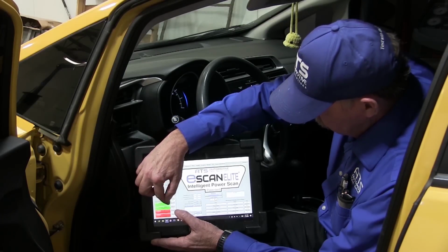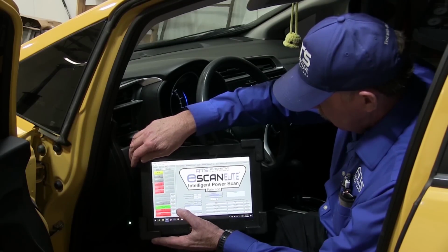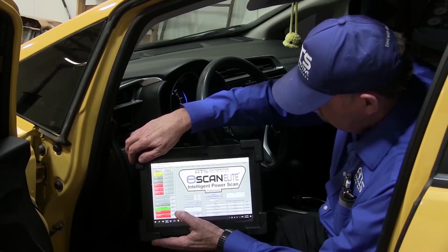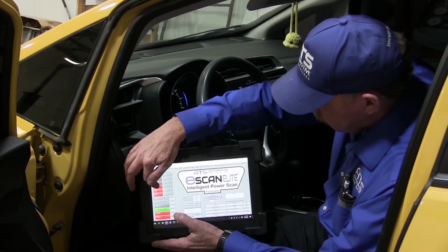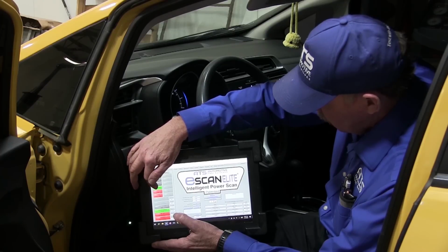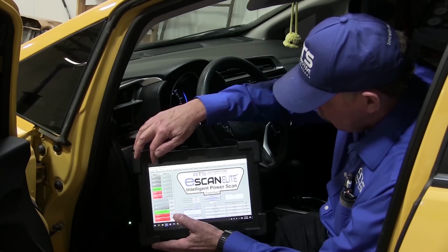We have good engine vacuum. Let's go ahead and just raise the throttle and see what it does. Now we're just staying rich with a control problem. So we don't have enough trim to fix it. That's what that tells me. If I can't get into a stoichiometric condition and I'm rich, I don't have enough trim to fix the problem.